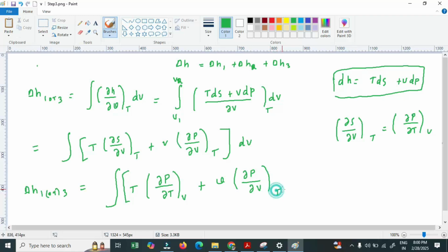So here, 1 to 2. Now I want to replace this dou P by dou T in terms of V. Therefore, I can integrate the step. For that, since it is a high pressure system, let me assume my system follows the Redlich-Kwong equation. That is nothing but P equal to RT divided by V minus B, minus A divided by T power 1 by 2 V,